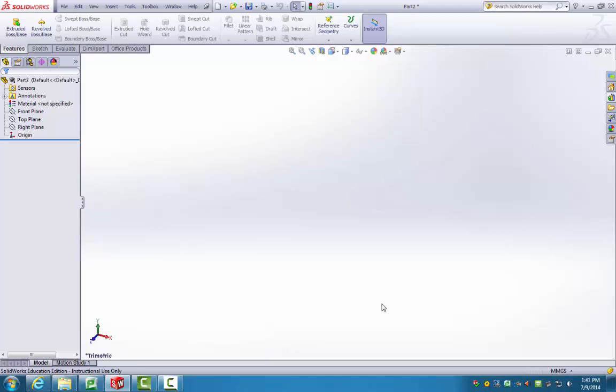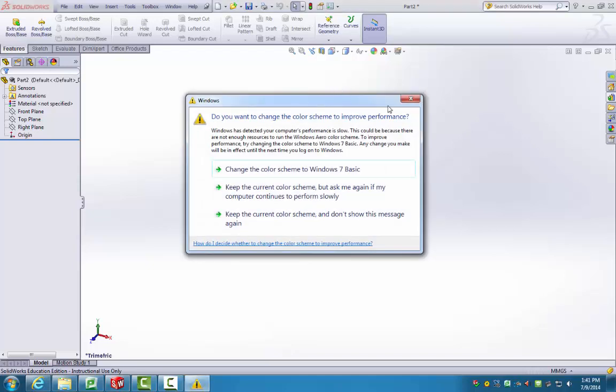The snapping to corners just gives you an easy way to approximate how large it is, but any of these dimensions that you assume based off of the units are not going to be strictly enforced or fully defined unless you define them via dimension. And generally, if you're defining it via dimension, it's not any more difficult to just not have the grid lines in the first place. So I won't be doing that particular portion. For those of you following along, I will be getting started on page 312.